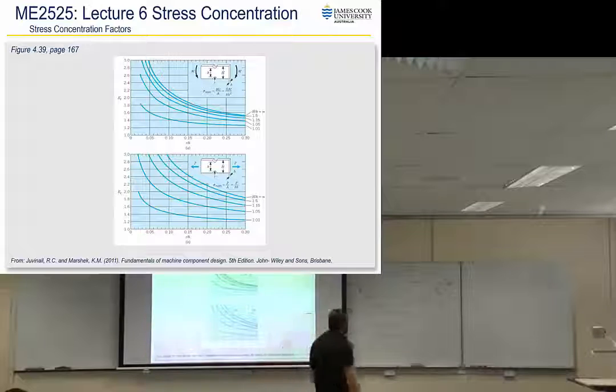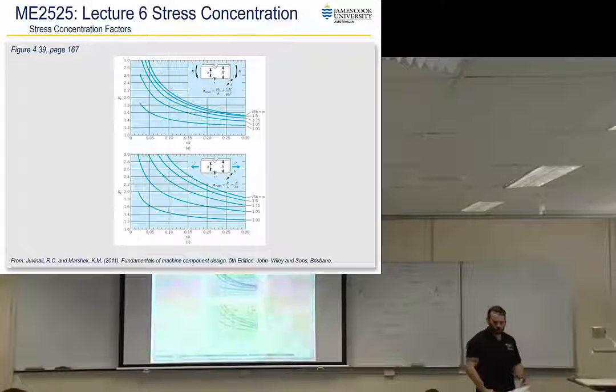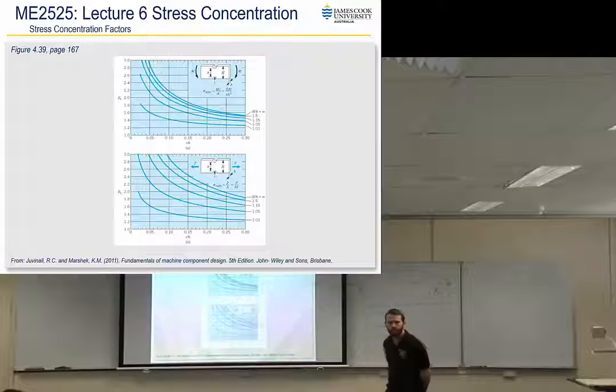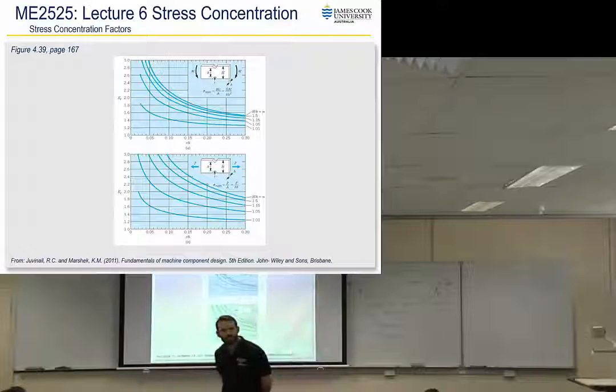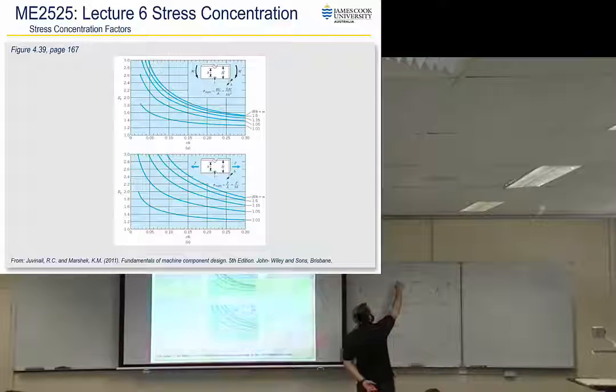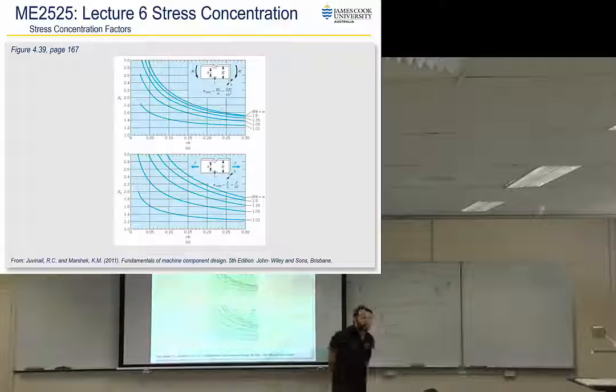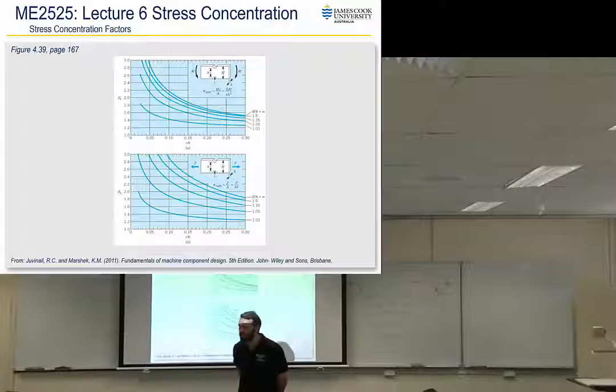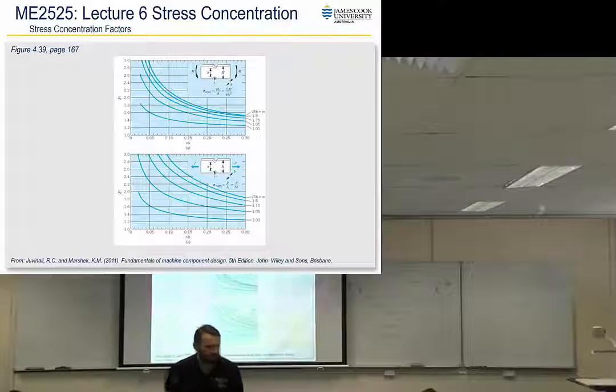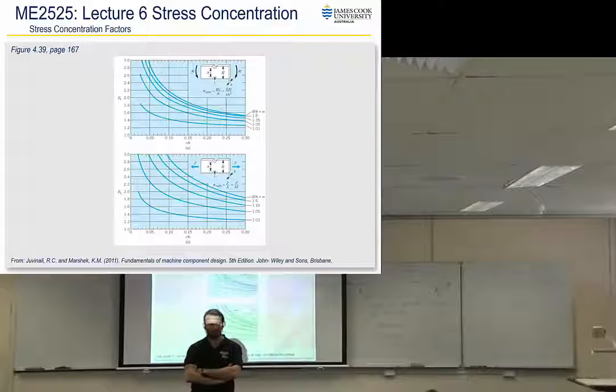We need a small h. Well, that's the question, isn't it? In the absence of small h, what would you assume? That the centre of the circle is along the top edge of the shape. Exactly. In the absence of this information, you'd assume that that point along that edge is the centre of that circle. So you take 2r off 100 and you get your small h. Now that's not necessarily the case because that notch can be recessed down, but in that circumstance, unless I've stuffed it up, I'll tell you what the small h is. Or you can calculate it yourself or measure it or whatever.